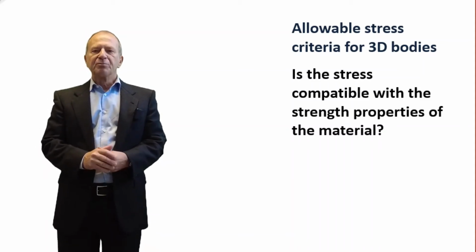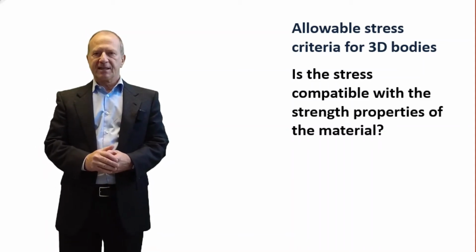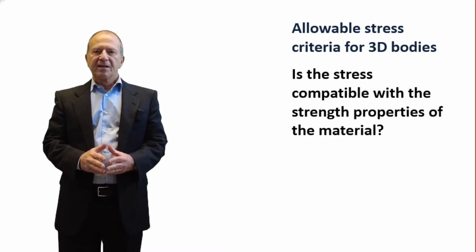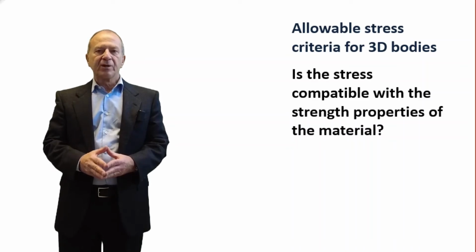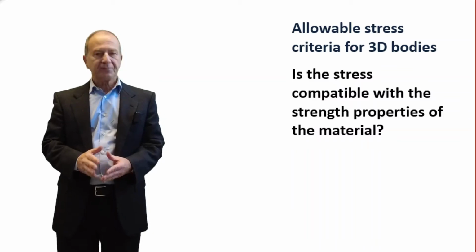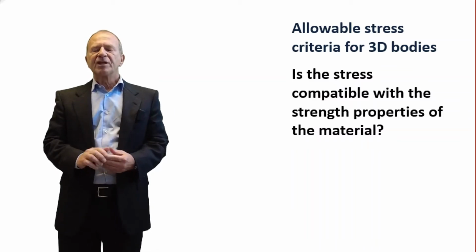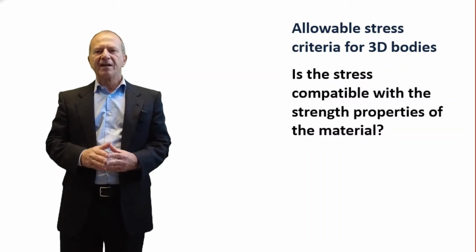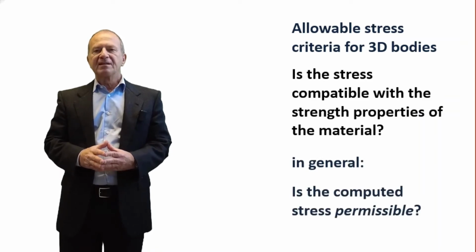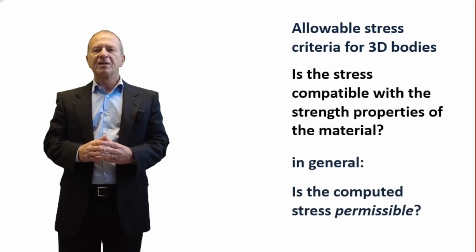If the stress was computed according to a linear elastic analysis, we must check that the material does behave elastically under the working stress. Otherwise, the computed stress will be simply meaningless, as it does not satisfy the assumptions under which it was computed. Well, generally speaking, we have to verify that the computed stress is permissible, meaning that it is sufficiently far from a condition that would make the material unsafe.